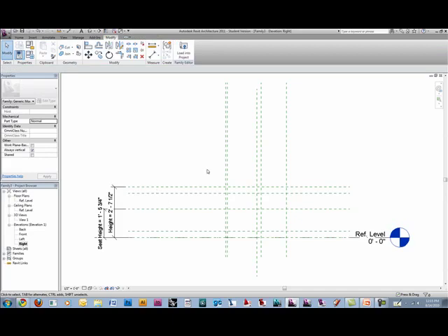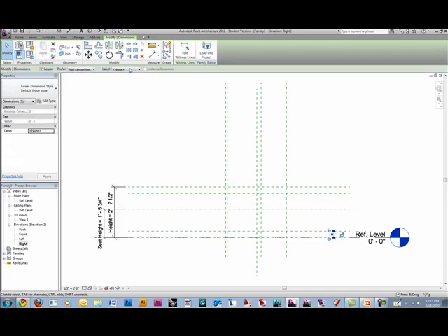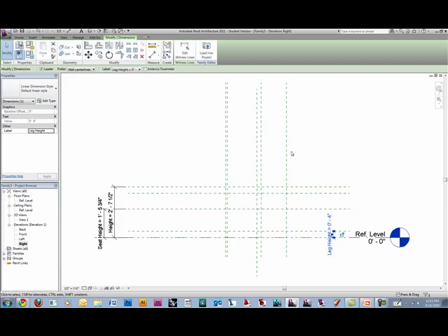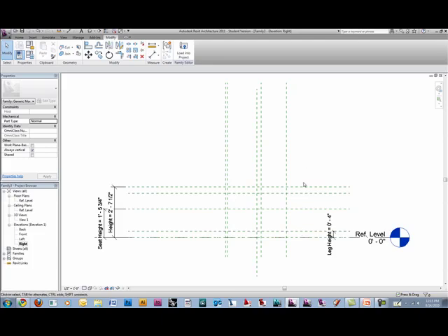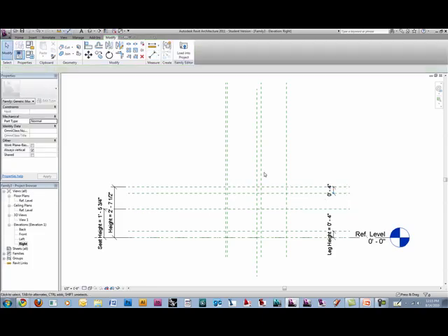And I don't have to constrain those to each other. I could say that this is from here to here, maybe the leg height. That way I could say that I need the legs to be longer or shorter in a project. That might be pretty cool. But the top, I don't really want it to change with the legs necessarily. I just always want it to be 4 inches. So that might be where we just use our little lock. And it's good to go.